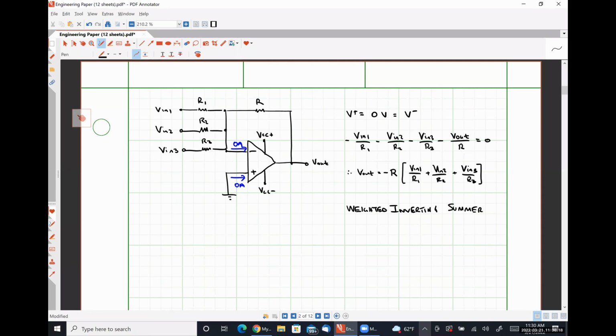As for a weighted inverting summer, if I were feeling really squirrely, I could compute your final grade in this course using an op-amp circuit, since your exam 1 grade is 20% or whatever, and your exam 2 grade is 20%. I could literally do that using voltages, but Excel makes it much easier. So if you need to scale things by different values, use a weighted inverting summer. If you want to scale everything by the same value, just make R1, R2, R3, etc. have the same value.